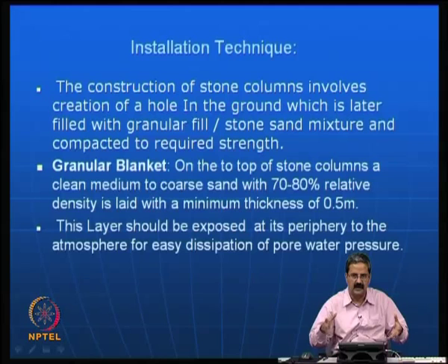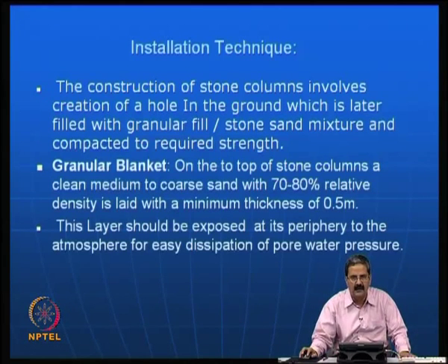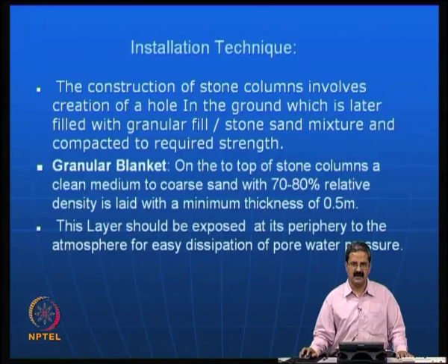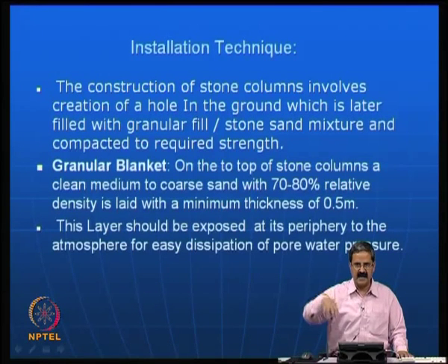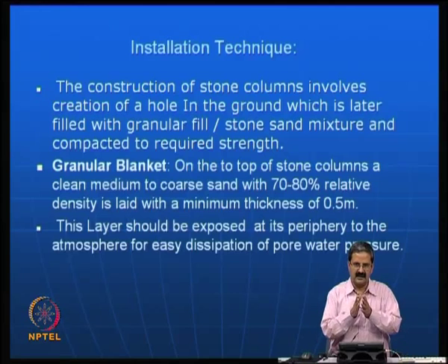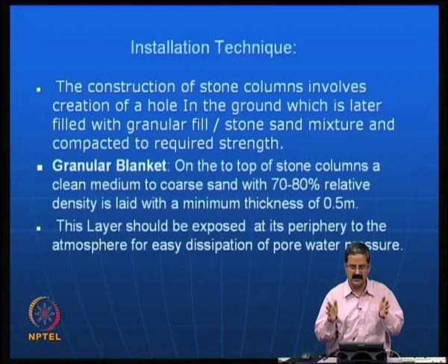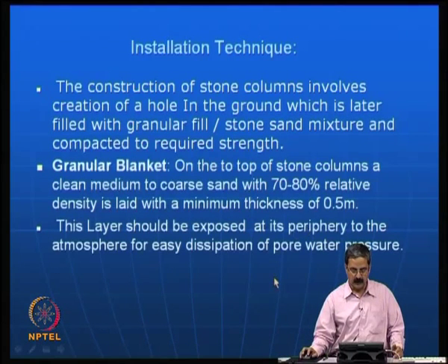So, there could be pore pressure mobilization in the soil. Clay soil always generates pore pressures, because you are trying to introduce sand or stone material inside, and then there is lateral pressure exerted, because the soil between the two columns is somewhat stressed. So pore pressure mobilization is a distinct possibility, and you should give an opportunity for the pore pressures to dissipate. So, what we do is provide a drainage blanket, and we see that the pore pressures are dissipated. This is one important thing.